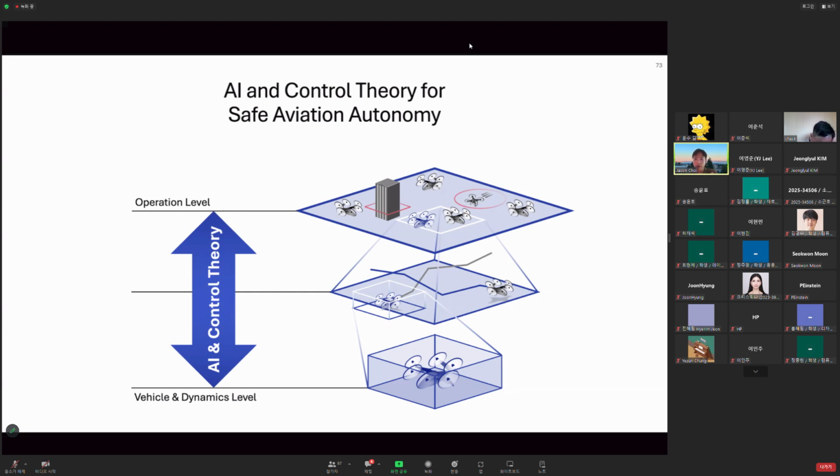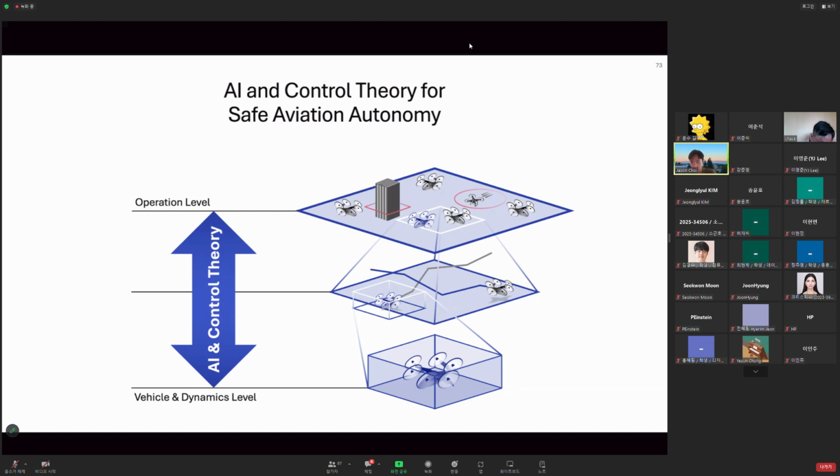Also, they don't have a good framework for bringing in information about the dynamics. So usually they only know whether the vehicle will be safe or not when the vehicle is close to a region where the dynamics can be linearized, because using a linear model for safety analysis is much easier. So definitely there are decades of work in the aviation community on safety for airliners and conventional vehicles. The main strategy is to allow the vehicle to only work in a very, very conservative operational region.